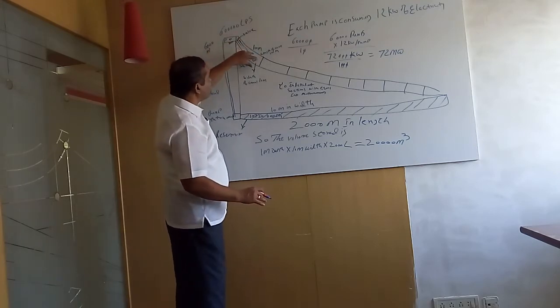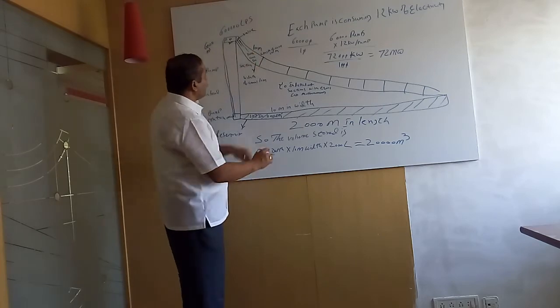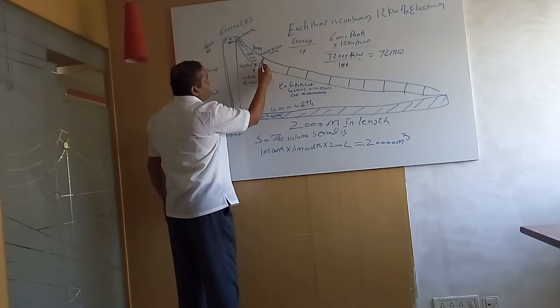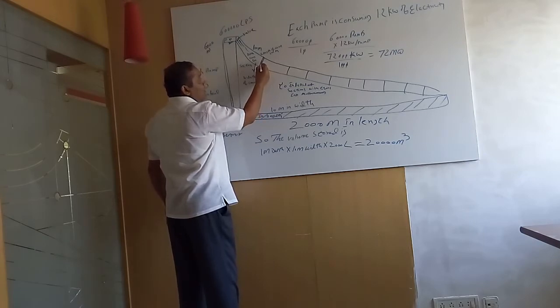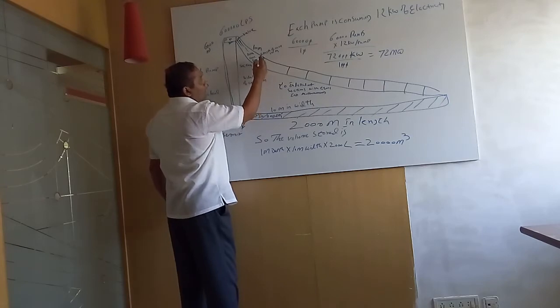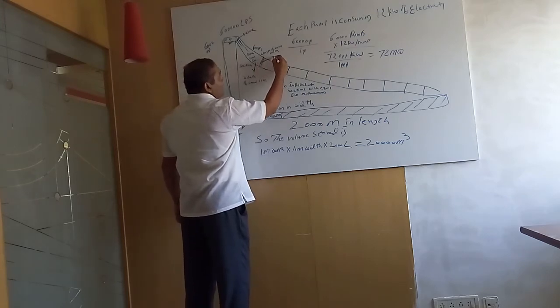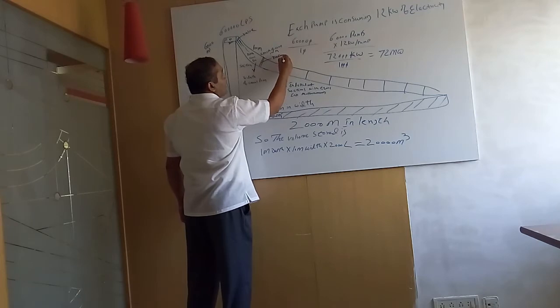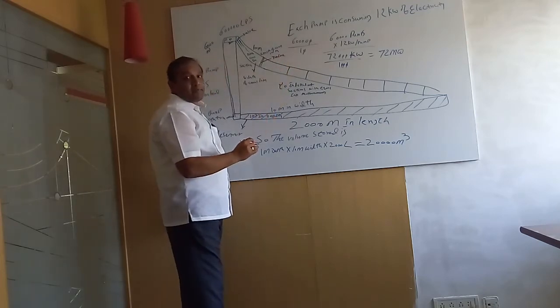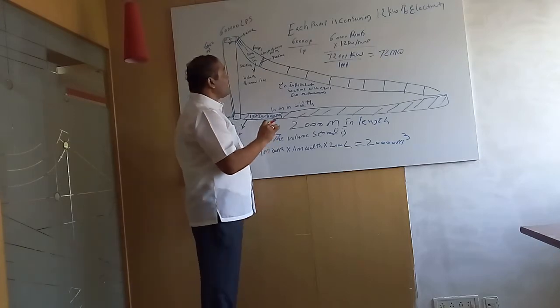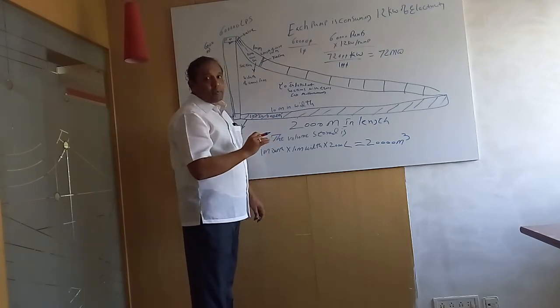So as soon as the water is getting filled in this particular sector, then a gate is there. This gate is open, or the valve is open, the radial gate or whatever gates we put to stop the water in the canal. So in this way, you will be having a turbine generator. Okay. A turbine is placed in the path of flowing water inside the canal, submerged inside the canal. This is called the bulb turbine or the tubular turbine.